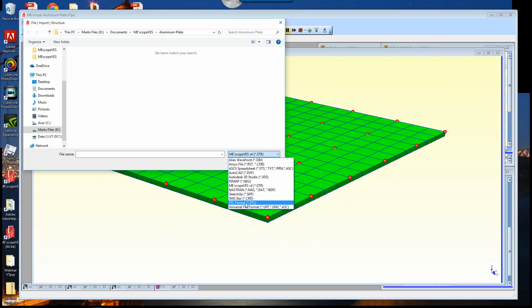But then you can attach all the parts together using SDM and using substructuring, what we call substructuring. And all you need are the mode shapes of each of the different parts of the machine or structure, and then SDM will put them all together, and you come up with a set of FEA mode shapes for a more complex structure. I hope that answered that question.